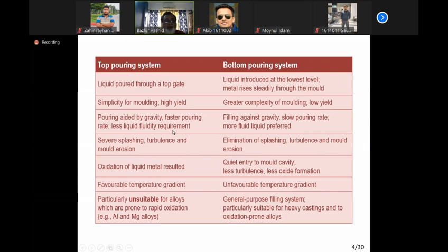We should mention this point because if you see the textbooks that we are following, for example, Heine's book, Bailey's books, all those books were written in the 70s or 50s even, 60s even. In that period of time, the only two metals commonly used were steels and cast irons, and this type of alloy has low fluidity. So one purpose of casting was how quickly we can fill the mold cavity. Fluidity is an issue because steel solidifies very rapidly. As a result, top pouring is always preferred, and all the gating systems used in those textbooks are top pouring systems.